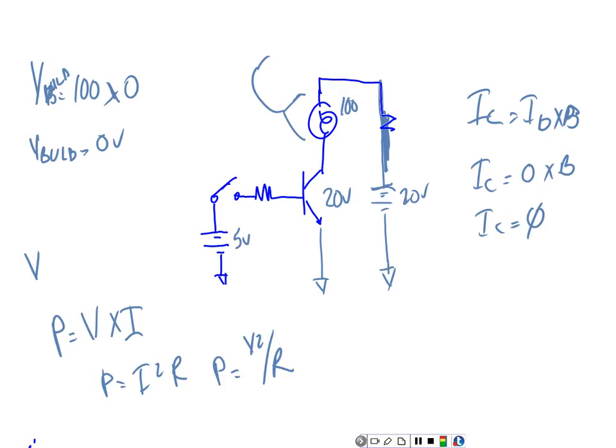So when I close it, we get current. When I open it, it's got to block the voltage, right? Just like fuses. Fuses are rated in amps and volts, because when they break that circuit, that voltage is trying to push that current through an open. When it breaks, we call it blowing for a reason. It creates an ozone arc inside there, and if we don't do something, current can conduct through that ozone.